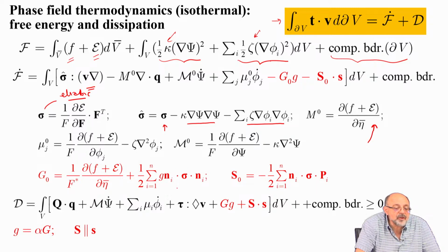This is a normal stress on the boundary. And this is the rate of change of energy. So why two terms? Clearly, normal stress on the boundary does work on lattice growth. But to produce that growth, you're creating new lattice with new energy, right? So there is a price to pay for that, and that price is denoted here.